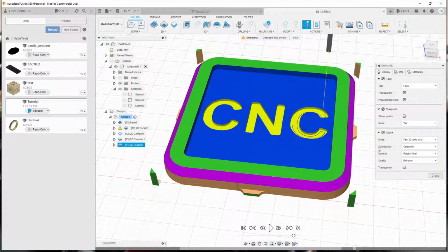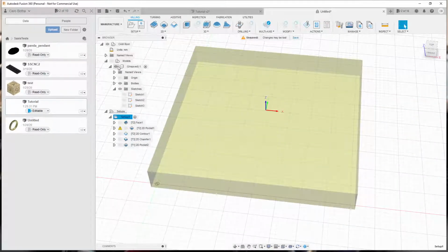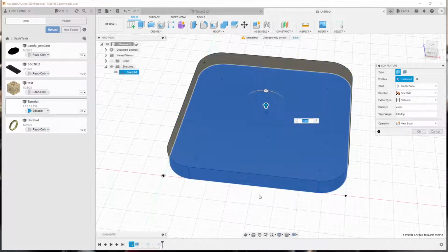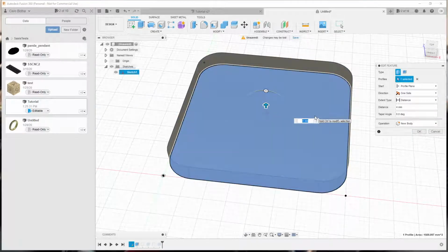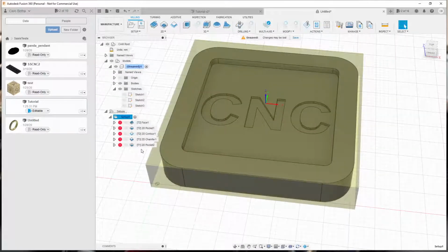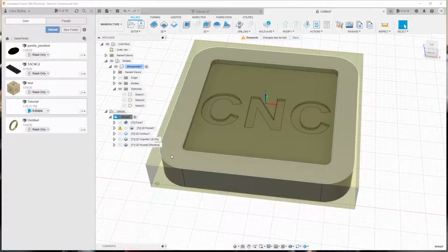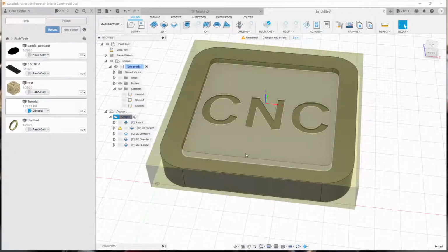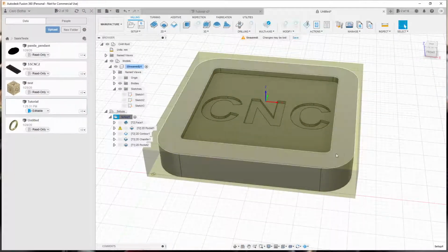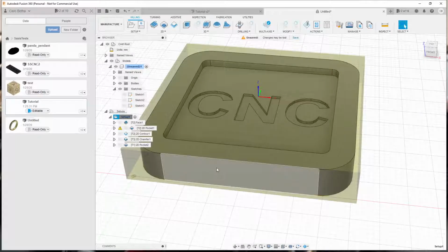And then again, like I said, because the entire thing is parametric, any of these changes you wanted to make, you can jump all the way back through your model line. So this original one was extruded to 4, and I don't know, Andrew said, oh, let's make something a little bit thicker for the customer. Just press 6, the entire drawing updates. All right, you just go to design, you go back to manufacture, regenerate, hey presto, you're done. Quite a dramatic design change, and you didn't have to do all that work, draw it all again, regenerate all the paths. You just click the little thing down there and you change the number.